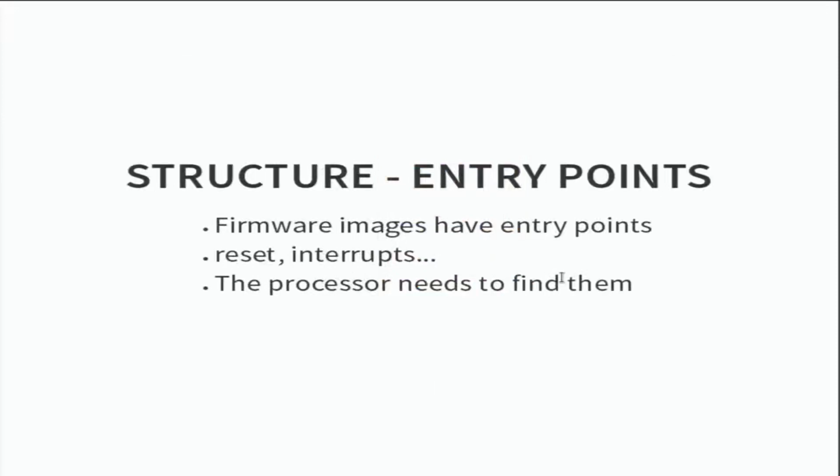But there's other structure in firmware files that we can use to our advantage, and that's that they have to have entry points. So this is a loadable module. It's not a piece of firmware that runs right on the microcontroller, so it might be a little bit different. But still, either the ROM that's going to be talking to this loadable module, or if it's just the raw firmware for the processor, still needs to get to the part of the code that you want it to execute. So it's a very common feature, and you actually heard some of this being talked about in the last talk, to have a vector table. And the vector table tells the processor, hey, here's where you're going to execute in the case of a certain instruction, certain interrupt, or for example, at reset.